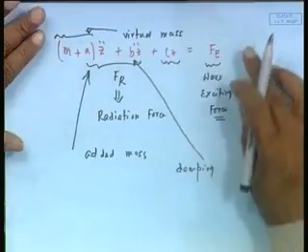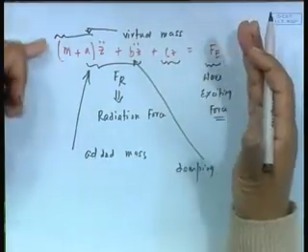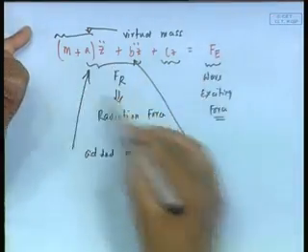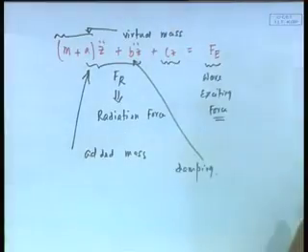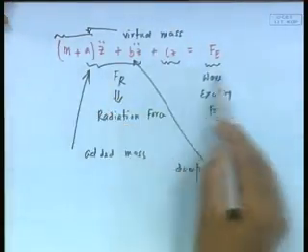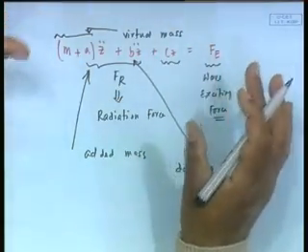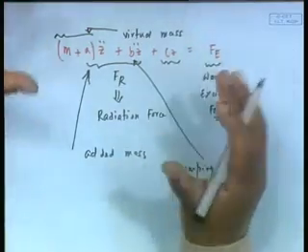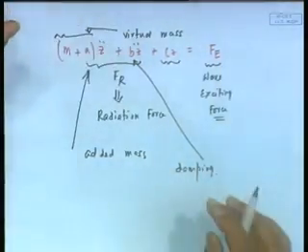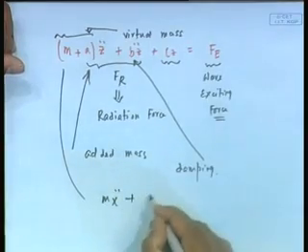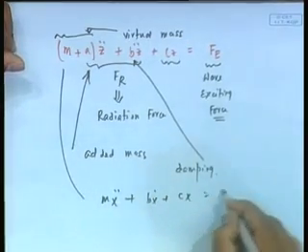That is one point, but what I showed here is in principle how we get an equation of this form. Having said all this, we end up getting an equation of this form, which of course looks very similar, or is the same as, any vibration equation: m x double dot plus b x dot plus k x equal to f. That is any forced vibration equation. Absolutely straightforward as a forced vibration equation, the same as m x double dot plus b x dot plus c x equal to some f.